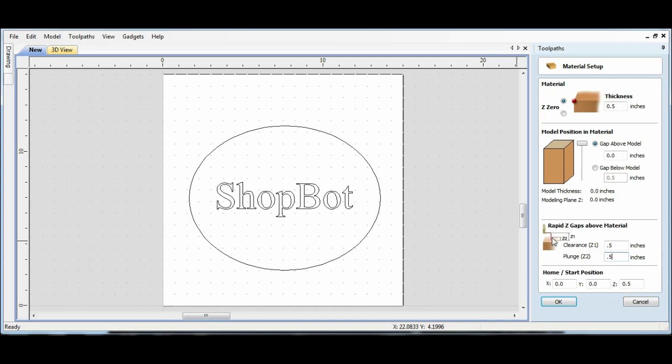And if you ever have any questions, there's typically a little picture over here that'll kind of help guide you in what those actually mean. The home start position, when we zero the machine, that's going to be the home. So if I changed my Z to 1, and when we go over to the CNC machine and I tell it to go home, there's a little command, which I always do, it's kind of like the last step I do to make sure that I zeroed my machine properly. I'm going to tell it to jog home, and it's going to jog.